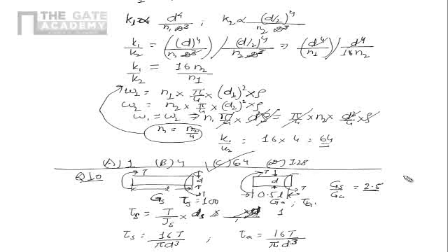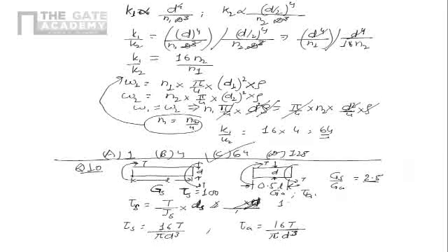You see, length, the ratio of G, and D, all these are given to confuse us. Because the diameter is not changing and the torque is not changing, the shear stress cannot change. The shear stress in both aluminum and steel shafts will be equal, and everything else has been given to confuse us. So please be careful of such questions. They can be solved very easily, but they are given to confuse us.